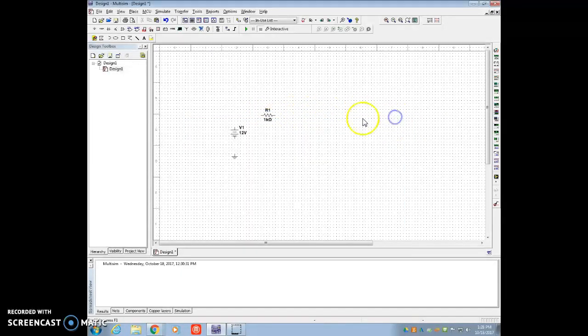I'm going to close this now because everything else I can do with the components I already have. I can click on R1 and press Control C to copy, and Control V to paste myself another one. I can also paste a third one with Control V, and I can rotate that by pressing Control plus R. This is also in the tutorial if you need a refresher on that. Now I have 3 resistors. I can always drag the components around if I want to move them. This is basically the setup for your series circuit.